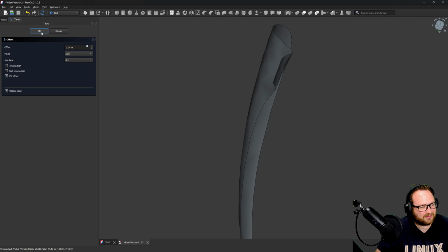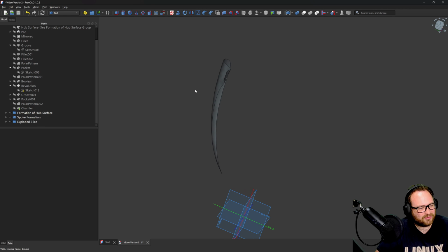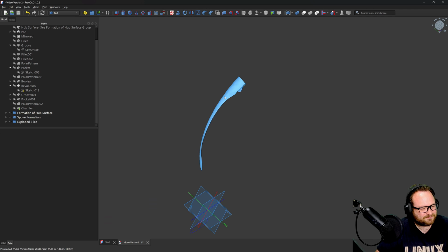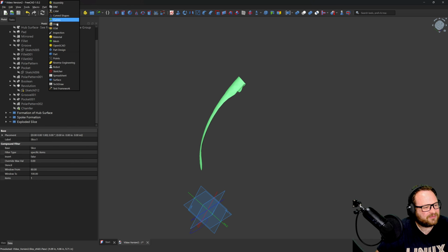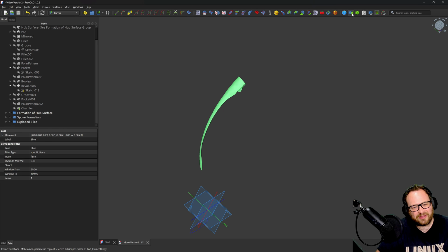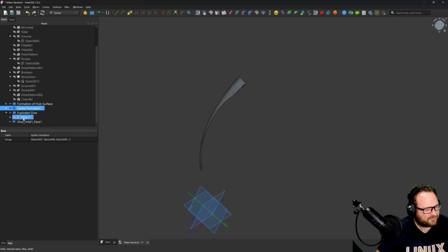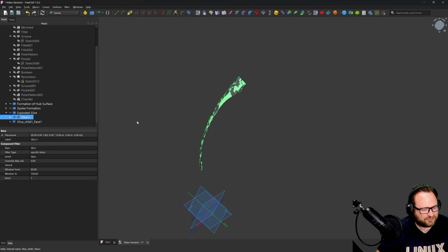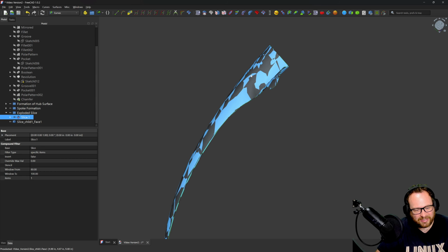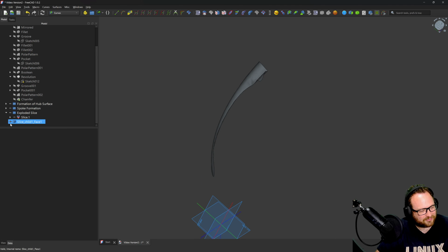If I try to fill it, nothing happens, and we're just offsetting it a millimeter. So there's not much hope that that's going to work. But I think what I can do is select this surface. We'll go to curves and we'll select subshape. That essentially duplicates the surface, right? And in that we should have, yep, we've made our exploded slice invisible, so I'll show it. You can see the graphical mesh there between the two identical surfaces.